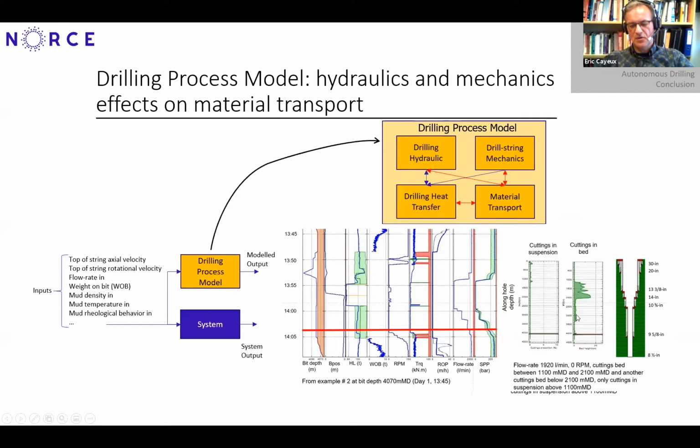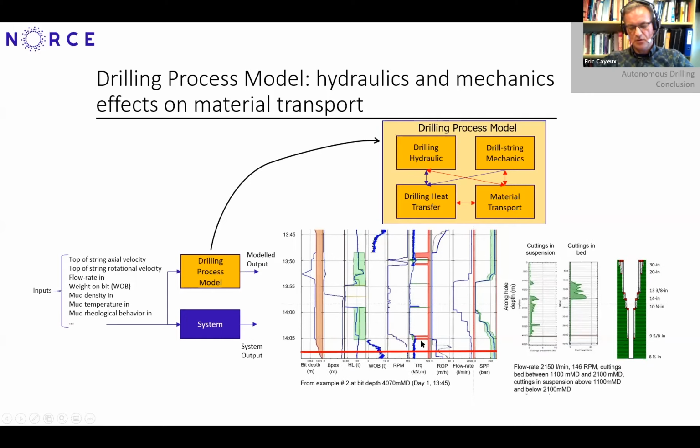They are still left on the low side, because only circulating without the support of the rotation of the pipe is not sufficient to return those cuttings particles up to the surface, to the high velocity field, which is on the high side of the cross section. It's only when we put the rotation in again that those particles are lifted up from the low side